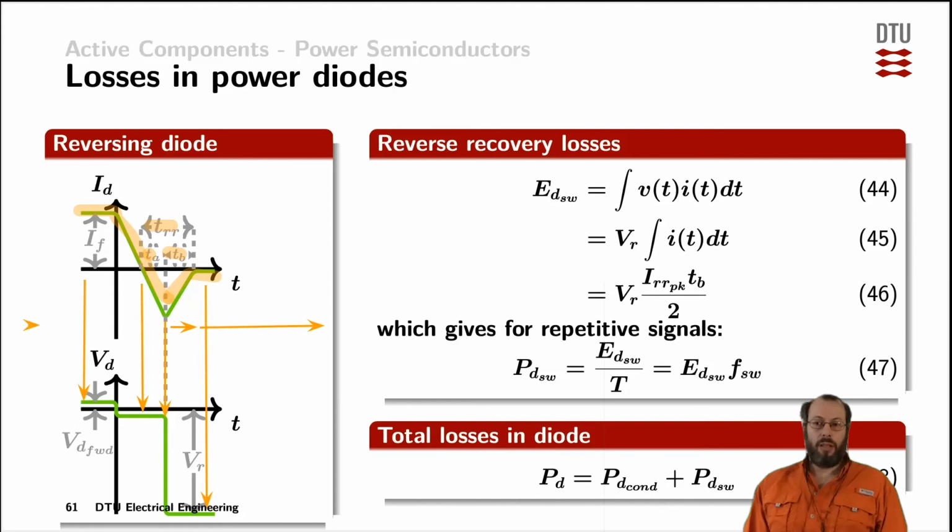And after that, it would cycle. The diode has been conducting for a rather long time compared to the nanosecond actions that are happening during the reverse recovery event, and we start from the beginning again.